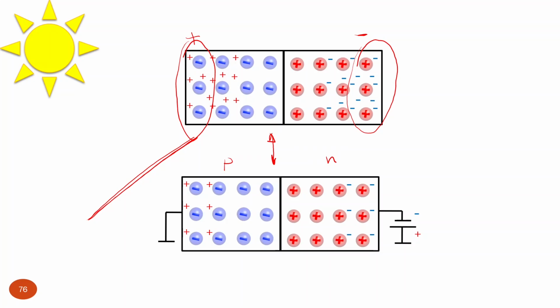So because of drift of the significantly increased concentration of minority charge carriers through this p-n junction, we start to accumulate, in open circuit condition, you see, we don't hook up here any load resistor, these drifted charge carriers as majority charge carriers already on the opposite sides of the p-n junction, and they create some space charges, which act as if we would apply external bias.